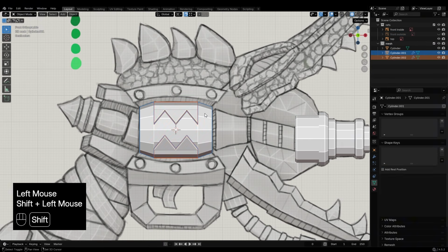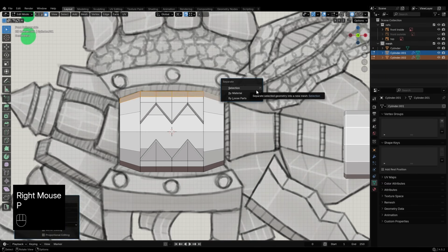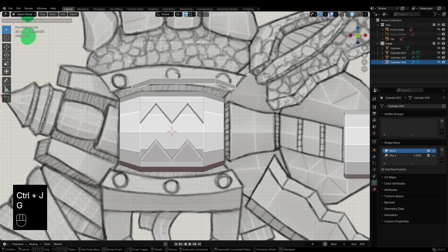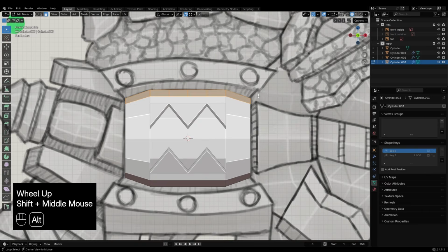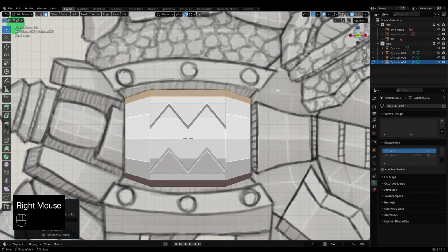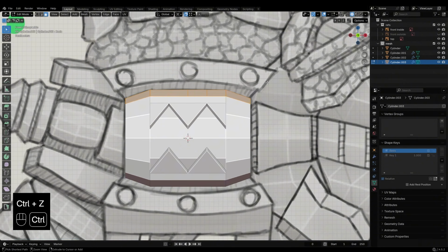Select both meshes, go into Edit Mode, and select the top faces, then duplicate them, separate, and join them into a single mesh using Ctrl+J. Go back to Edit Mode, then try to extrude faces along normals. But here, the extrusion direction is flipped. As a workaround, you can press G then Z to move it upward. But let's redo it and understand why this happens.